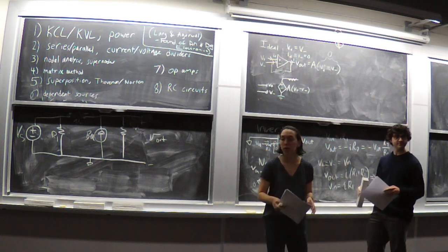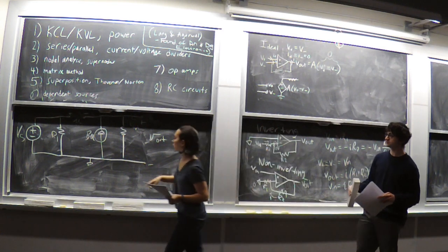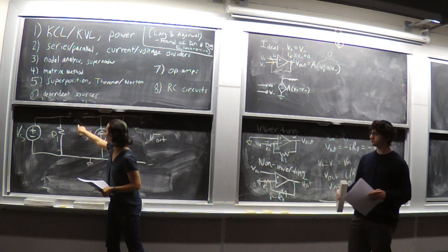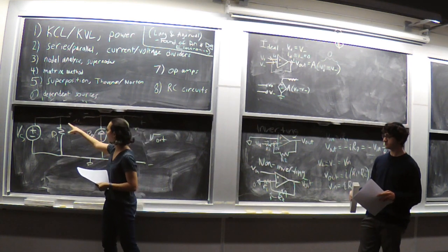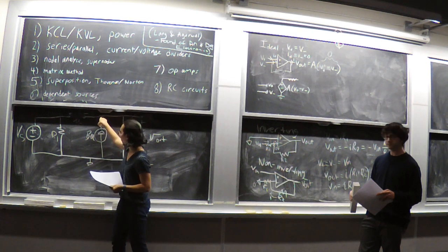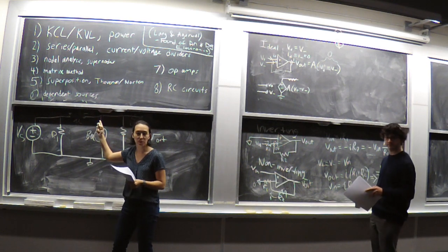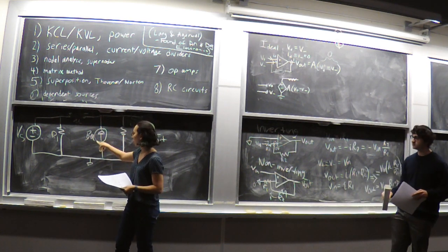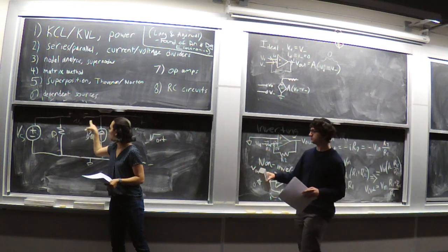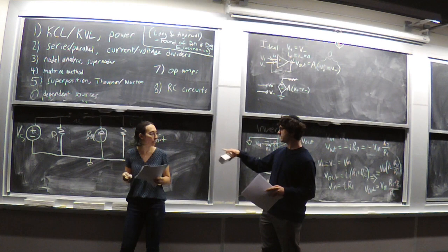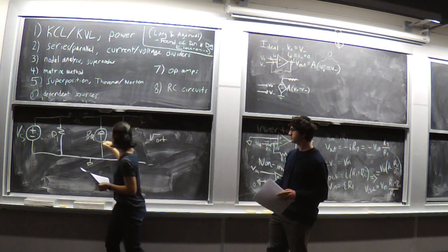What's the U? So the U is the measured voltage. It's not a voltage source. If you were going to take a probe and do a measurement between these 2 points, that voltage is U. So this is a dependent current source that is based on the voltage between these 2 points.